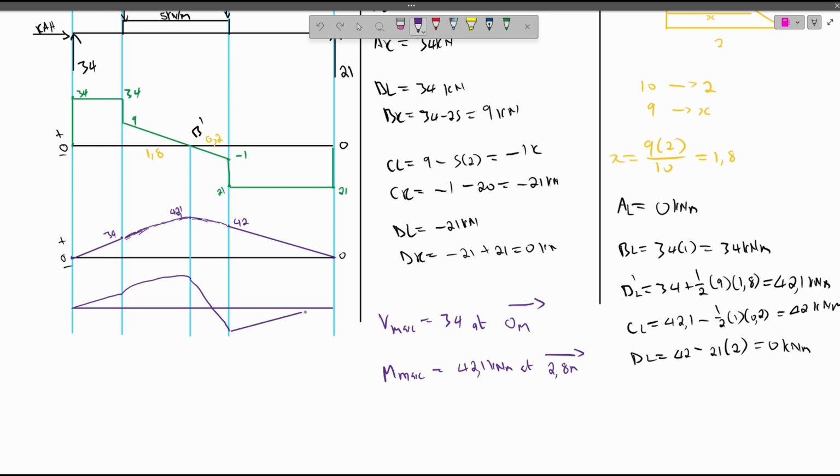Yeah, let's say this was your shear force. You open the moment diagram. The point of contraflexure is going to occur at this point. This is the point of contraflexure. To find this point, you're going to take moments. You're going to cut your beam at this point, which will be somewhere here. You'll either use this part of the beam or this part of the beam, and then you take moments at this point using the forces that side or the forces this side of the beam, and then you find your X.